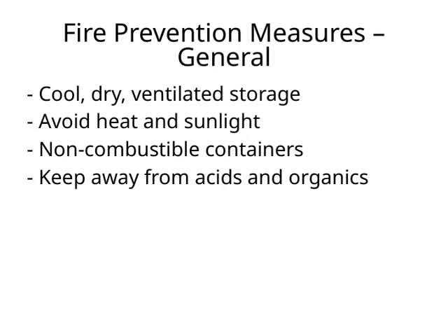Let's talk about some essential fire prevention measures for storage. First, it's really important to keep your materials in cool, dry, and well-ventilated storage areas. This helps prevent any buildup of heat or moisture that could potentially lead to fires. Next, always avoid exposing your stored items to heat sources or direct sunlight, as these can increase the risk of ignition.